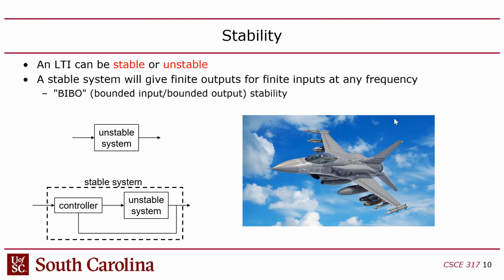So you have the manipulated variable here and the process variable here, but then the top level input, kind of from the user's perspective, this is a set point. And so if you combine the unstable system with the controller for the purpose of stabilizing it, you end up with two transfer functions that you connect in series, and then that whole system can then be stabilized. So, that's what's happening here, is that it's stable in the sense that I can put a set point in here, and I don't have to worry about the system blowing up.